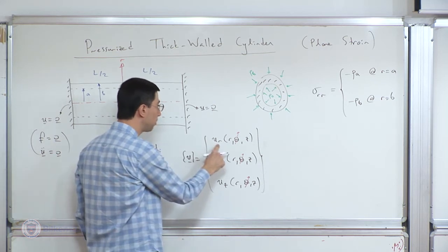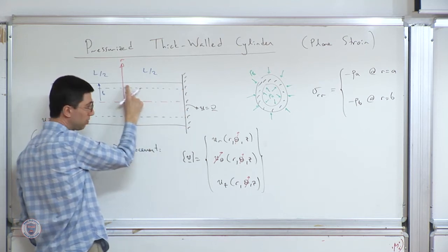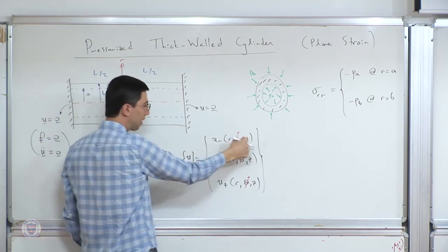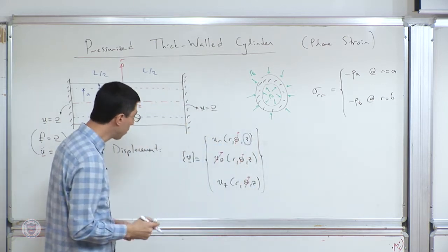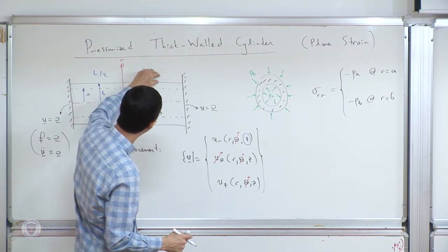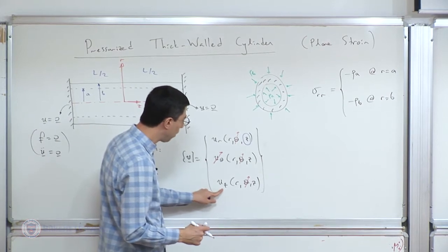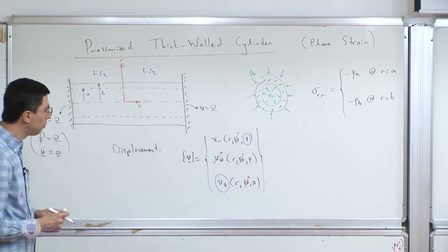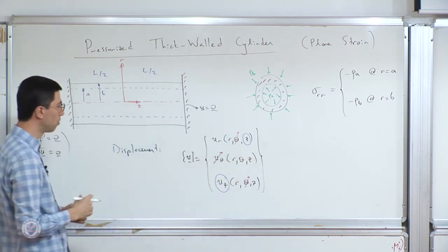Now, there is going to be a radial displacement. But the radial displacement at this point is fixed. At this point, it's not. So obviously, as I move along the axis of the cylinder for this original setup, I cannot immediately eliminate this z dependence. So this is a bit of a problem for me presently. Likewise, eventually this thing is going to deform in a strange way. So it's fixed there, and then it will blow up to a larger radius, come back down to the fixed support. There is no reason why I should omit U_z from the outset either. And now if I want to solve the problem in this setting where there is no U_theta, whether it depends on theta or not doesn't matter. U_theta is 0.